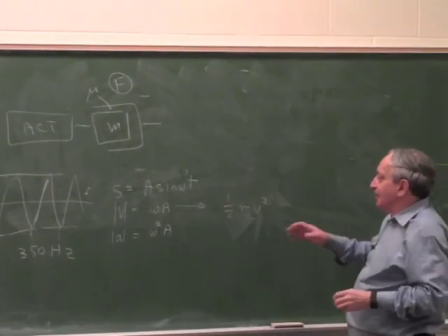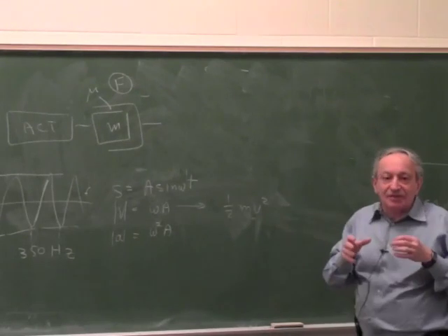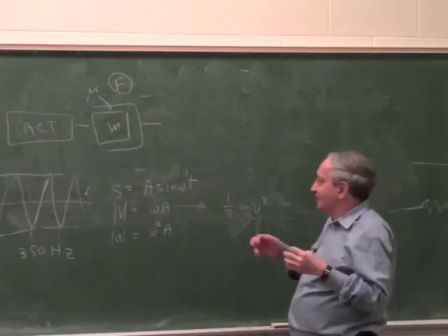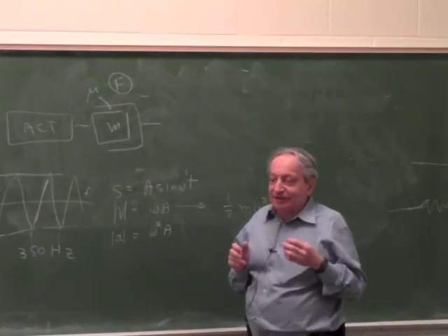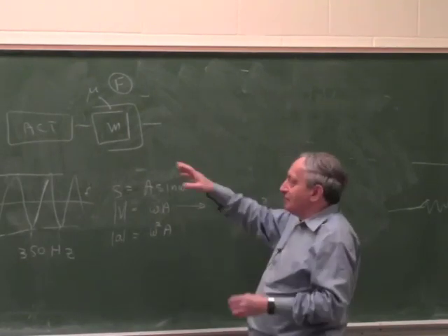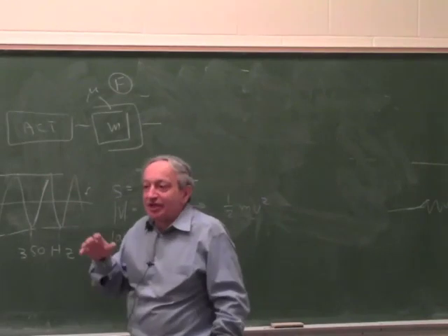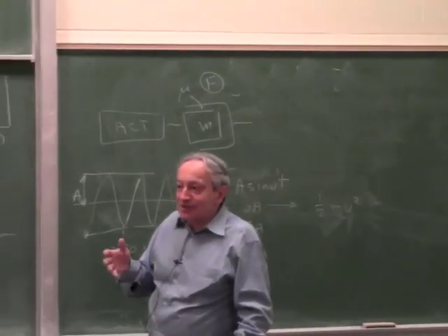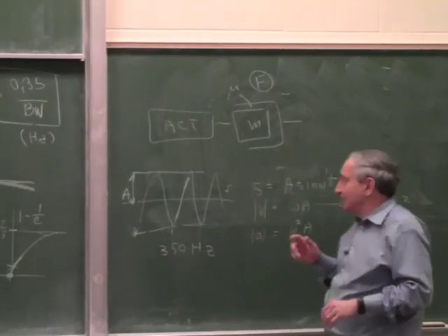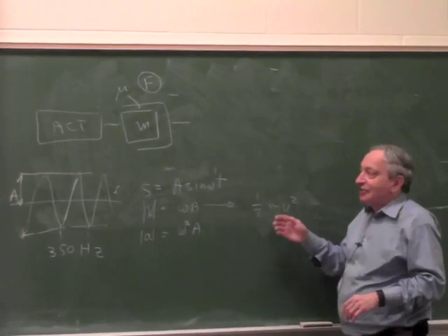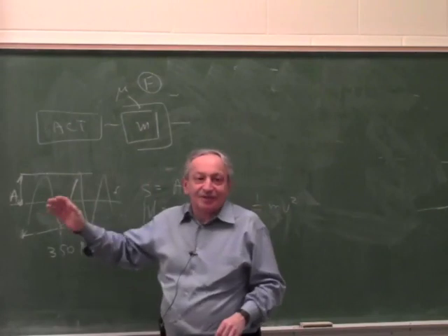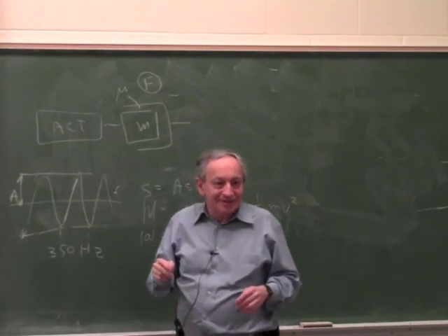So per cycle, this is a part wasted on inertia. Now, of course, there is a fine argument here, because this energy is recoverable. If I have a mass and a spring, all this is recoverable. But this ties to the question of whether a servo has regenerative braking or not. Since most simple servos don't have regenerative braking, to the servo this energy is not recoverable. You have to accelerate the mass all the way, and you can't count on it coming back, like with a spring.